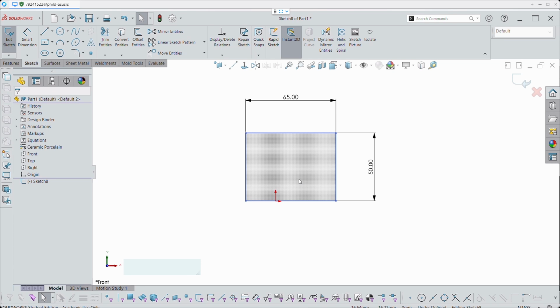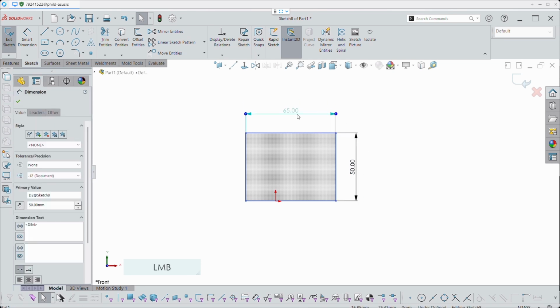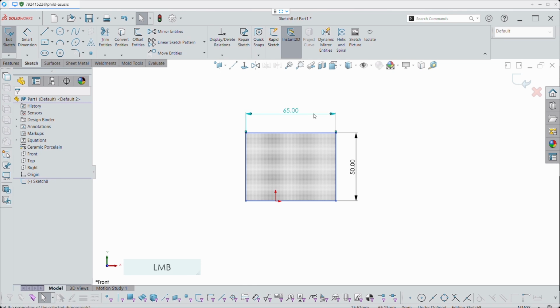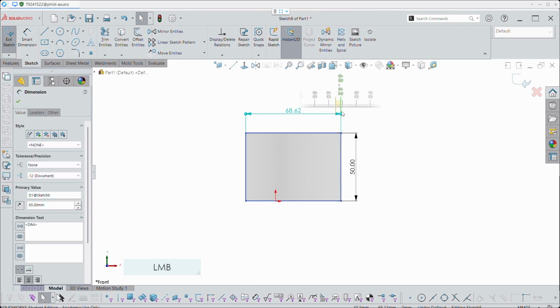So my rectangle is now horizontal, but I would also like it to line up with the origin at a center point. So at the moment, it's defined as far as the dimensions go. And if I click on a dimension, I can drag out. I'm not sure this isn't working at the moment, but I should be able to click onto the ruler and it'll snap to that. Oh, it is working. But if I drag this out outside of the ruler, you can see I can go in increments of 0.01. And if I drag it into the ruler, I can go into increments of 1 millimeter.